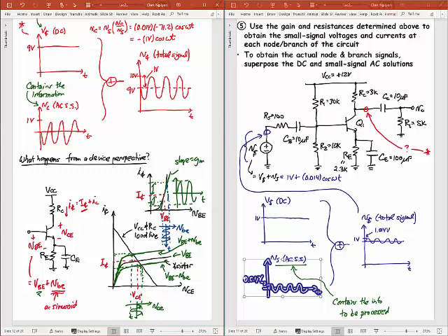Okay, so if you want to look at this physically, what's really happening, I'm wiggling my VBE, that's causing a change in I sub C, and that change in I sub C and wiggling in VBE is causing these curves to move, that I sub C is moving as well across this, and so where that load line intersects this transistor is moving basically. So the intersection point of the load line with the transistor moves, and that's what creates my output here. Okay? Kind of a complicated thing, and so hopefully you understood that as I went through it, but if not, I guess you can go back and watch this lecture again just to get all of it.